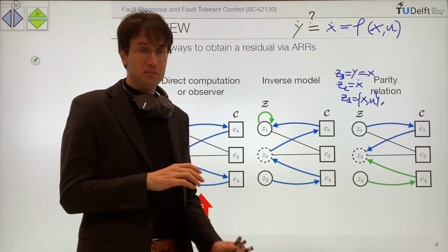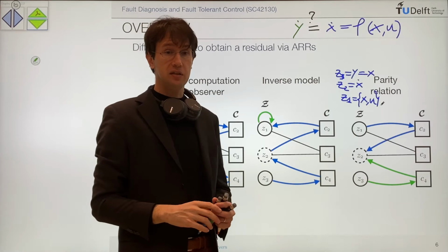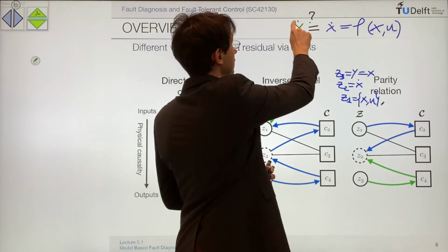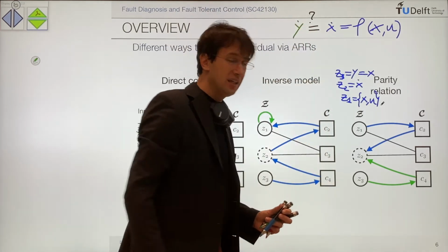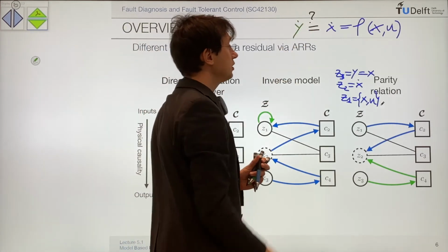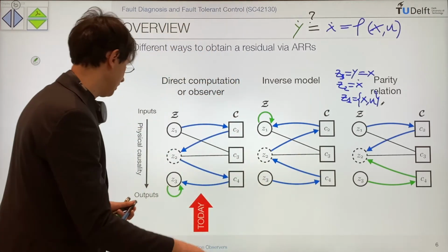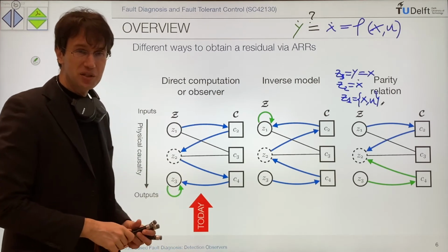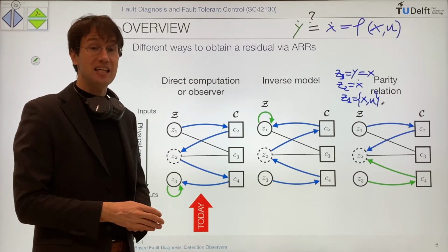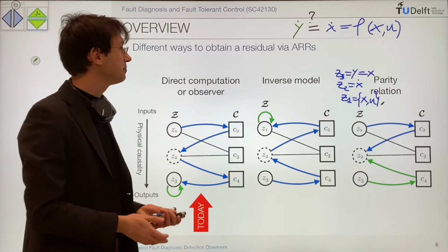There is anyway a big problem. y is affected by noise. So if you take the derivative, you're amplifying high frequency noise a lot. So checking this is really difficult because this is really noisy, computing this green y dot. There are some workarounds. You can introduce filtering of the output to reduce the effect of the noise. But then at this point, if you're filtering the output, you can just implement an observer, because the observer, if you remember the equation, is basically doing that. It is filtering the estimation error on the output in order to reduce the effect of the noise.